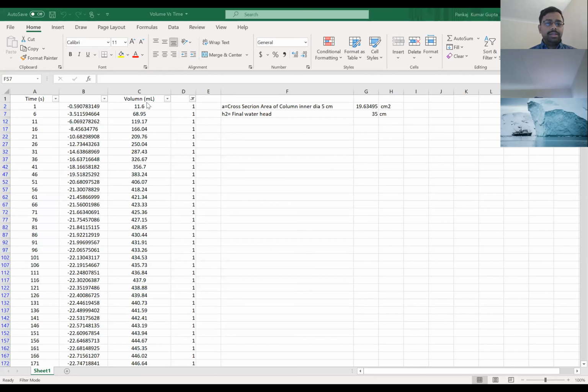you can see here the volume of water as a recharge was measured with the time step. So we are going to simulate this volume of recharge water through the domain. The volume recharge is known to us, and some hydraulic properties are known to us, such as the fitting parameter alpha and theta s.